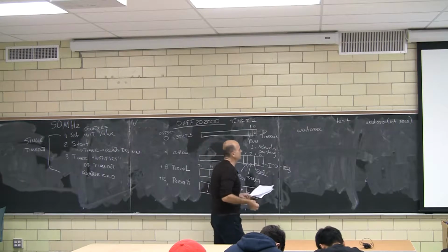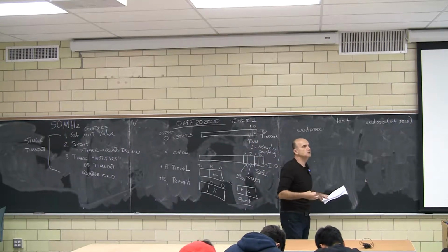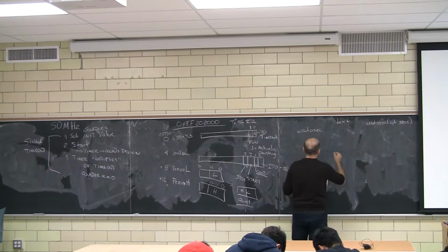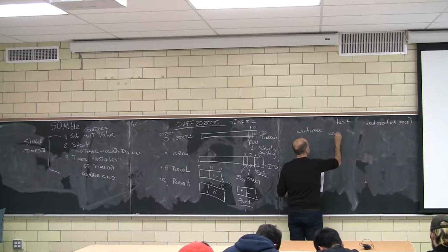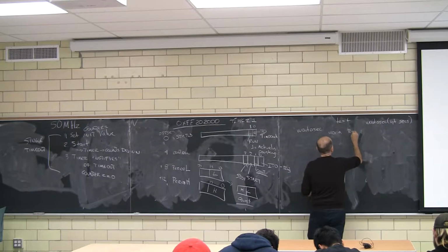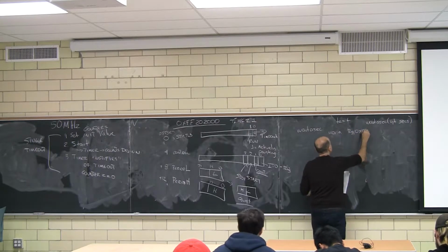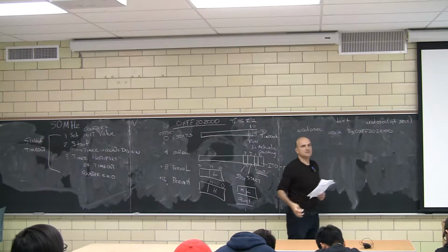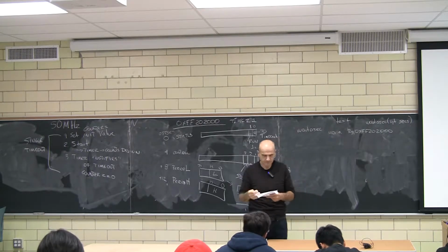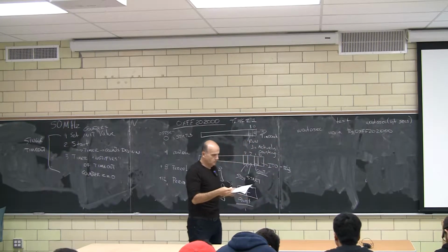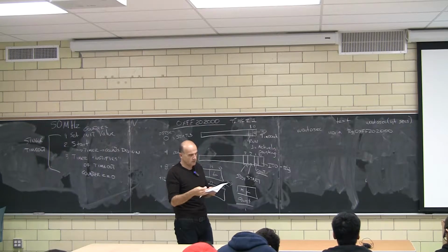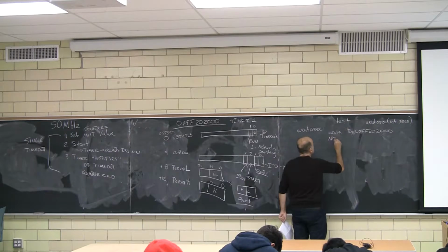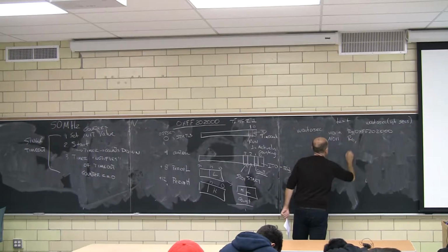Alrighty. First thing we've got to do, we've got to get the timer into a well-known state. So let's get a pointer, move A, let's say R5, 0xFF202000. So we get the base of the device. Next thing we want to do is stop the counter. Move R6, let's say.